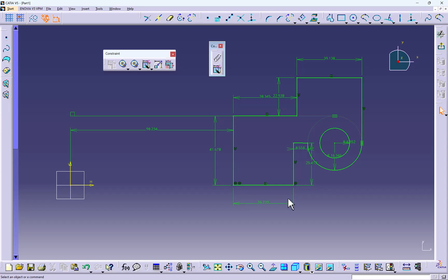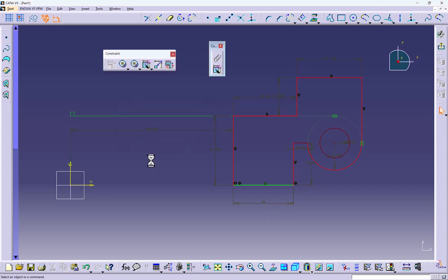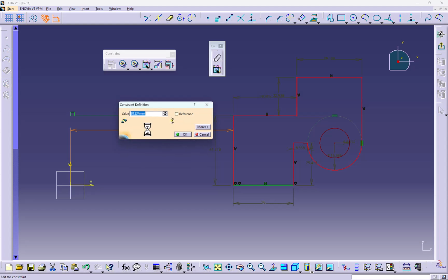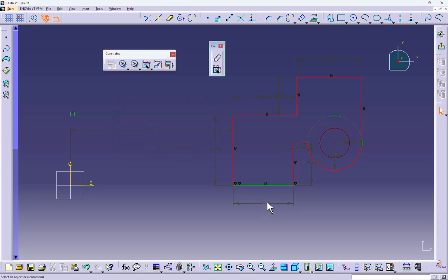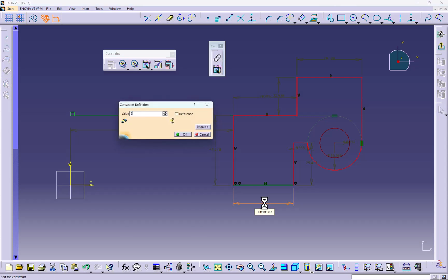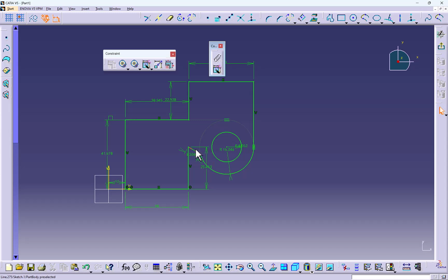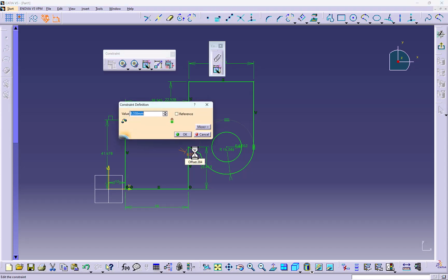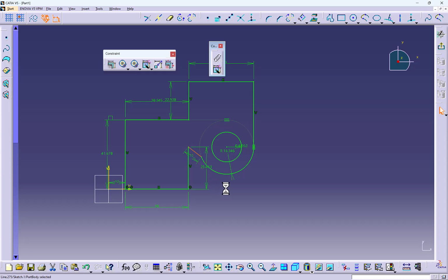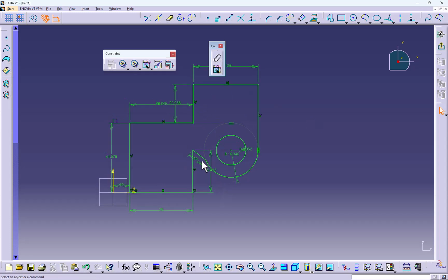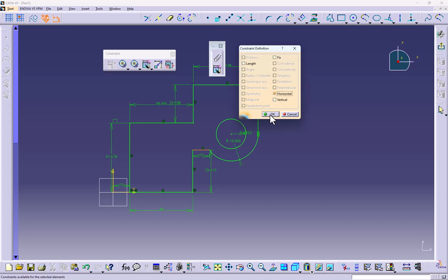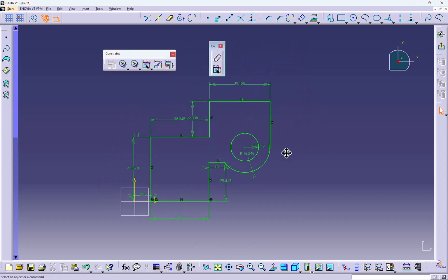Now, whatever dimension we need, we can adjust that by just changing the dimension value. Because when we change a dimension, since we haven't made it the proper size, it may cause problems, like the dimension lines causing problems, because the circle is there now. So you can adjust them by managing the relations, deleting relations. I deleted some relations from here, and we can add additional relations separately if required. So this is how we can use the auto constraint method in the software.